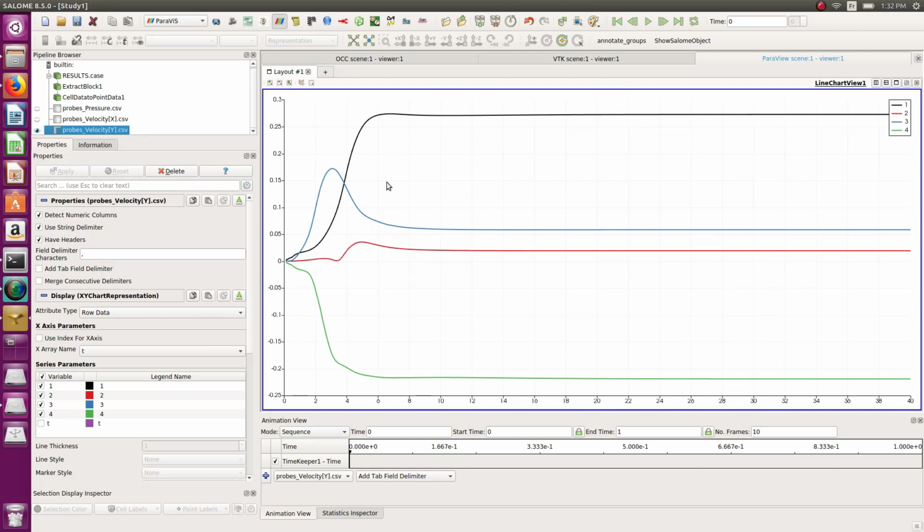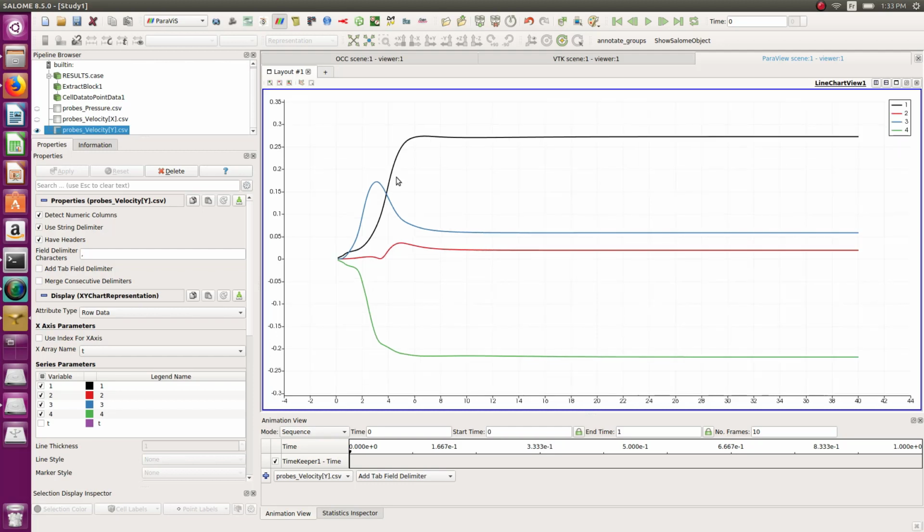If those curves, after 400 iterations, just diverge and do not converge towards a certain value, that means you either didn't define your model correctly, which is very possible, or you have to add more iterations until you reach convergence. Otherwise, the results you'll be looking at will not be your steady state results.